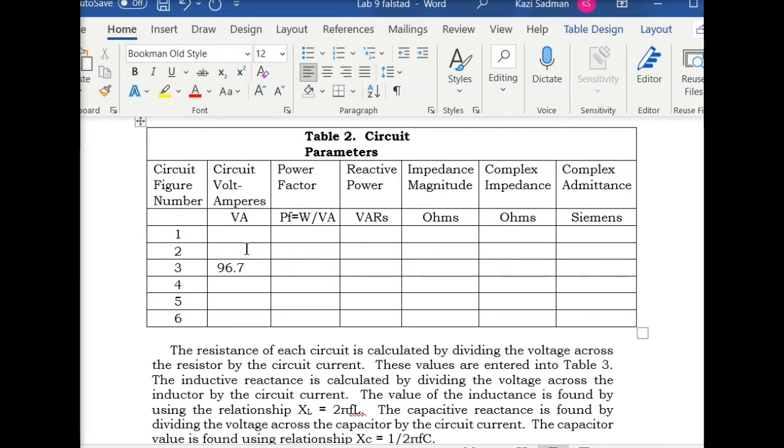Now what's my W? W is the power, the real power or the active power of the circuit. Since it's just a capacitor, the real power is going to be 0, because I discussed before that the power across the resistor is going to be your real power or your active power. Okay, so in this case we don't really have a resistor; we just have the resistor for the fact that the circuit is not going to simulate with just a pure capacitor.